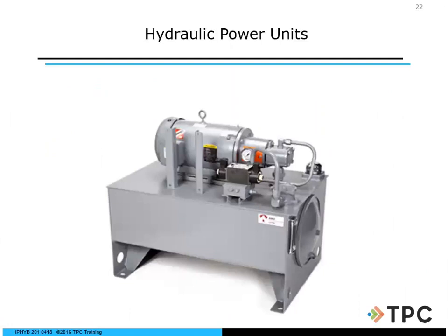Again, with my hydraulic power unit, you saw a symbol on that fairly quickly. So everything is together, and then we have our motor to pump. The thing about your hydraulic power unit, again, is make sure it's clean, clean, clean. Usually it all depends on how big it is. You can put a PM on this to change your hydraulic fluid.